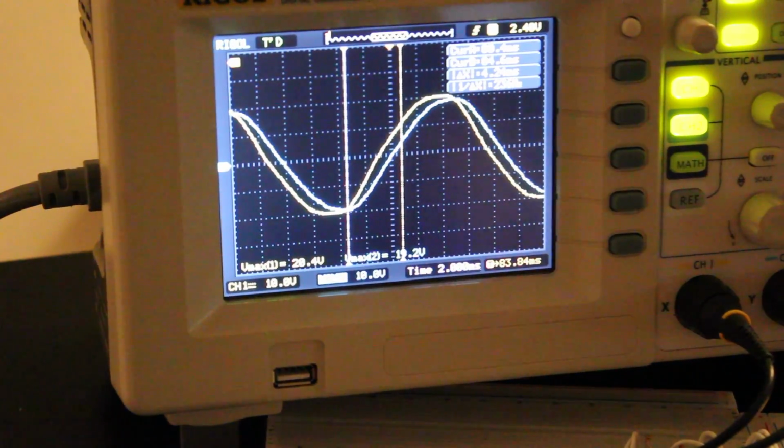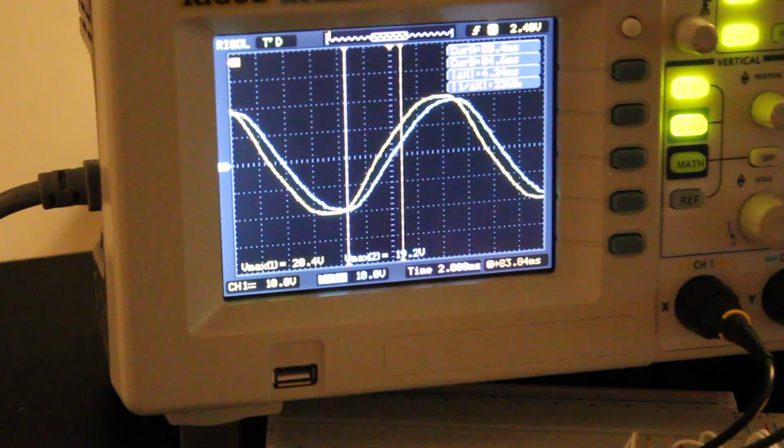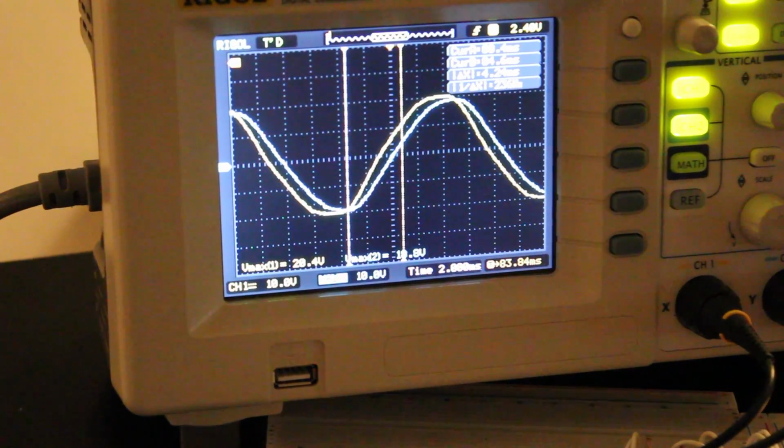So we're way under that. This is a low pass filter, so we're way under that, so the gain is hardly changed, but there is a phase shift. And I already calculated the phase shift out, and the phase shift is about negative 20 degrees. Okay, so that's what negative 20 degrees looks like.